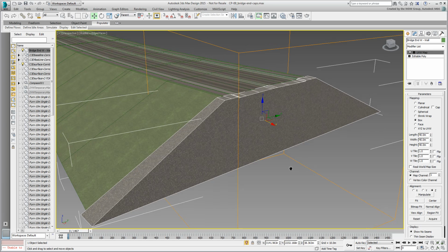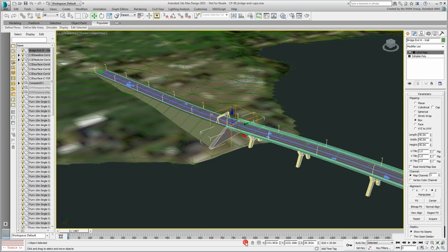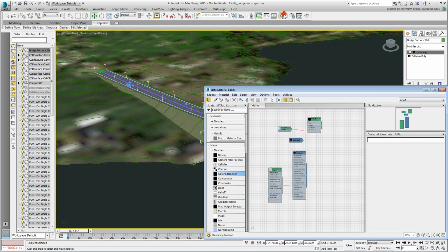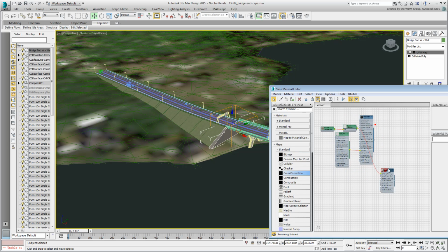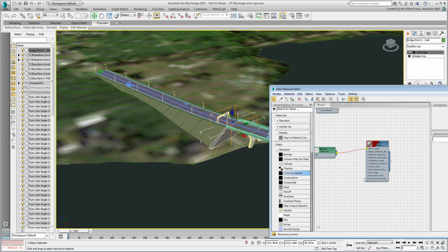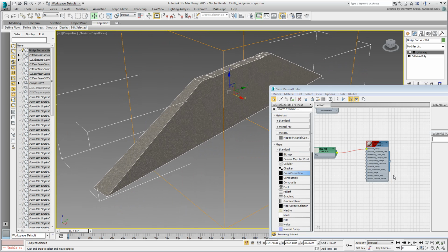Ultimately, you may also consider a different material for the wall. Perhaps use the same material you created for the pillars. For that, you'll need to temporarily exit Isolate mode so that you can see the pillars, and go to the material editor and sample their material so that you can use it on other objects. Once that is done, you can concentrate on the wall again and apply the new material to it.